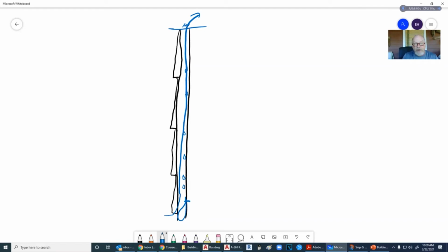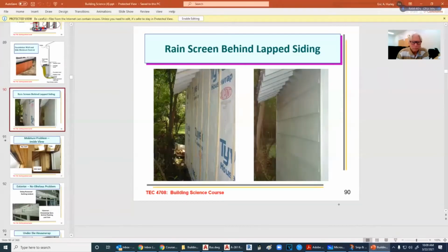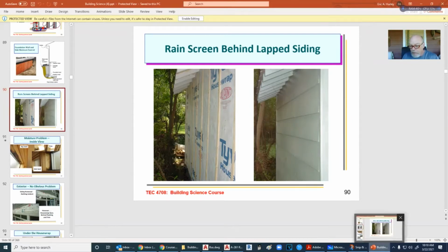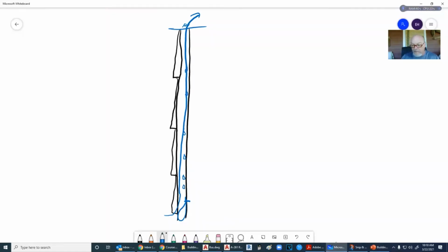So these are a good idea, but they're kind of a nightmare to build. Number one, if you're using extruded polystyrene behind this rather than plywood or OSB sheathing, then you've got to make sure that these are right on top of the stud that's in the wall. And one thing that personally I've had is a problem with the damn things busting. So, okay, I'm looking down on this portion here.